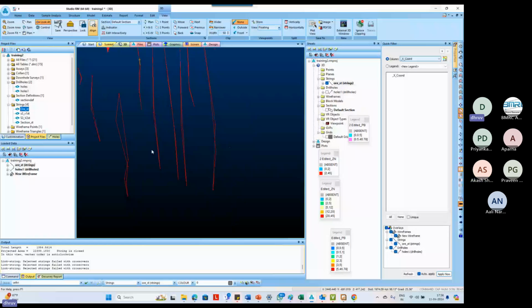I'll do that only. I'm not going to create another because of time as well. So I'll make it using the available information. I'll try to make it smoother. So NS, right click, right click. So I created a boundary string here also. Now, to create a boundary using a boundary string to link, the command is LBO. But before that, let us do the tagging first at the top.